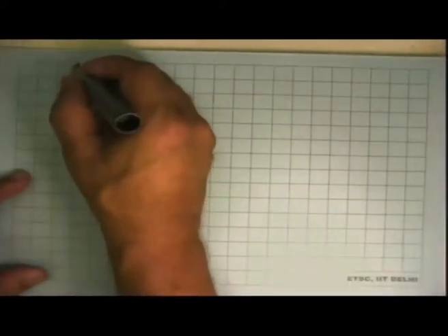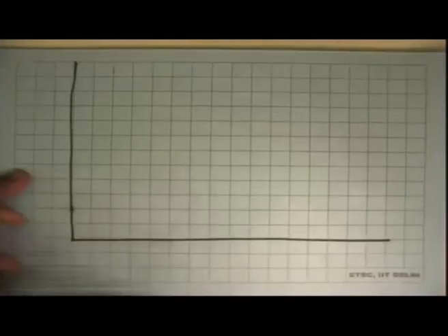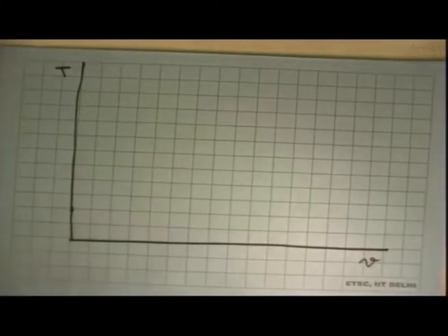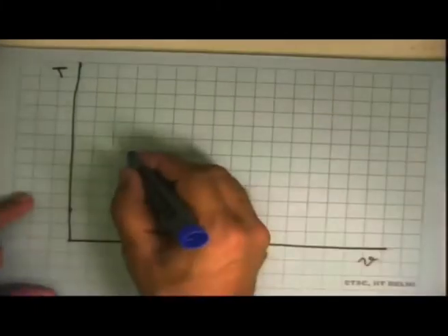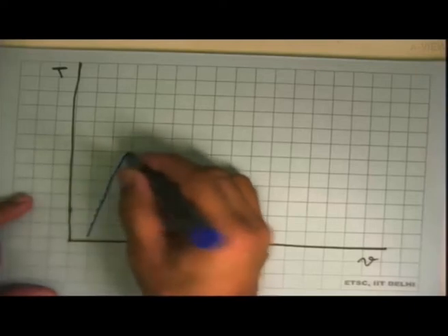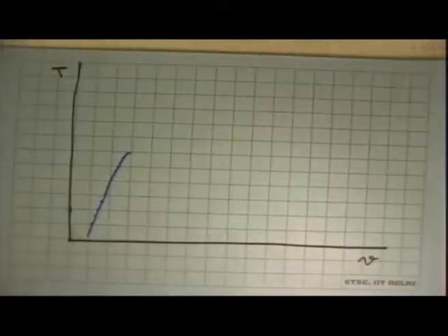So let's now look at some property diagrams. We also saw yesterday something that we have plotted, how this whole thing depends on the pressure at which this behavior is seen, and we came across two different sets of lines. We were making temperature on this axis and specific volume on this side, and we came out saying that there is a line which is like this, where each point represents x equal to 0. This is the saturated liquid line.